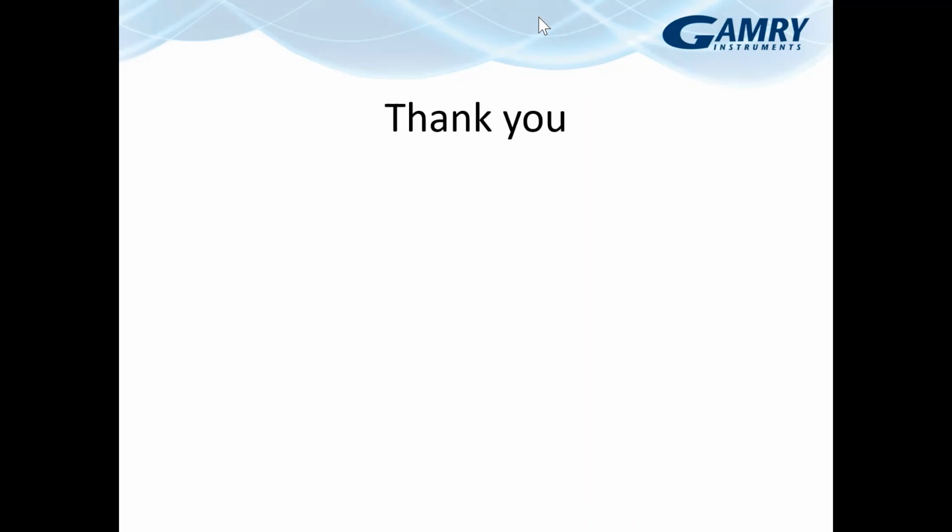Another question, can you give some examples of common good sources of earth ground in a lab? Most modern buildings, the ground wire lead is actually a good source of earth ground. Older buildings, that might not be the case. Older buildings, however, have a tendency to have cast iron and steel plumbing, and the plumbing is usually a good source.